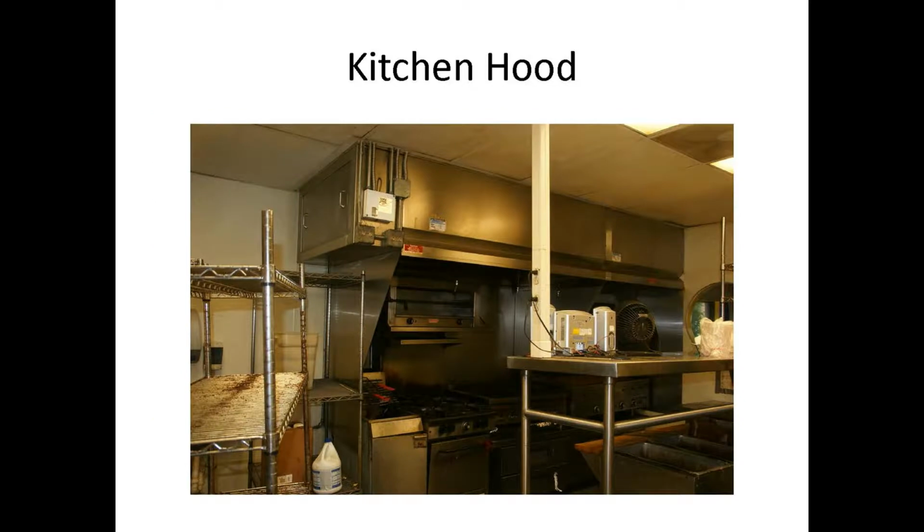Next slide. Another thing I do in my designs is the hood, the cooking hood in restaurants. These hoods draw an enormous amount of exhaust air out of the space in the restaurant. In addition to the hood, I have to design the makeup air, which is usually 100% outside air.